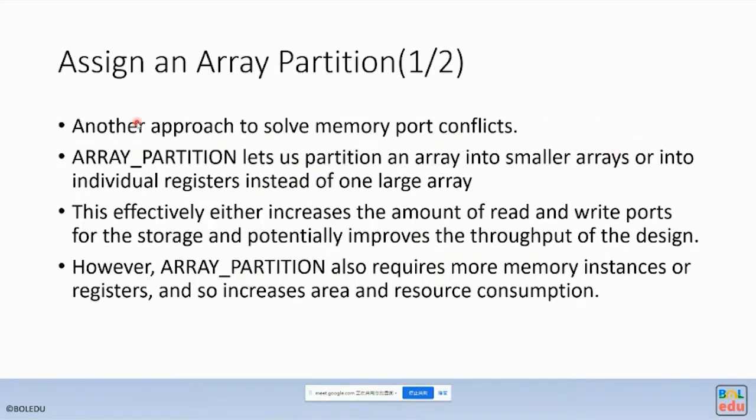And fourth is assigning array partition. Yes, and this is another approach to solve memory port conflicts. An array partition lets us partition an array into smaller arrays or into individual registers. This basically increases the amount of reads or writes for the storage and potentially improves the throughput of the design.